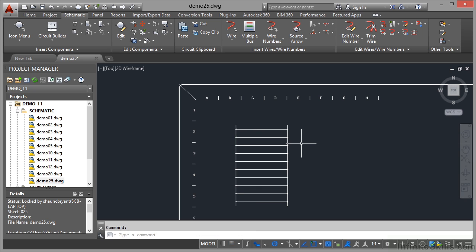And you'll notice this time there are no reference numbers on the actual ladder itself. That's because you refer to these here. So you've got B3 will be there, and so on and so forth. Ideally, you want to set up your ladder so that it actually ties in with the coordinates and the spacings. Now, I haven't done that in this case. You can see that that ladder does not tally up exactly with any coordinates on that XY grid.